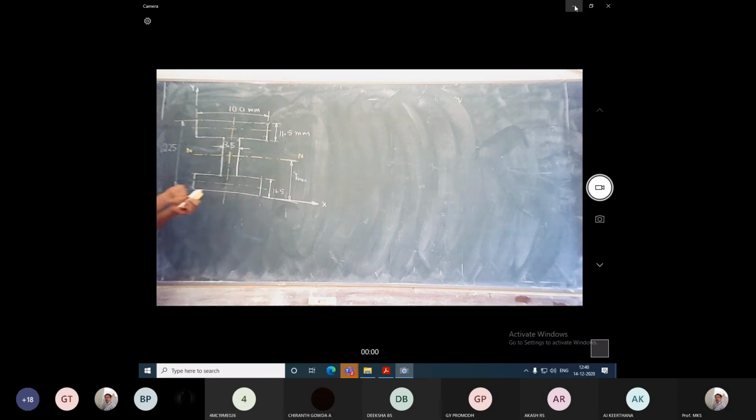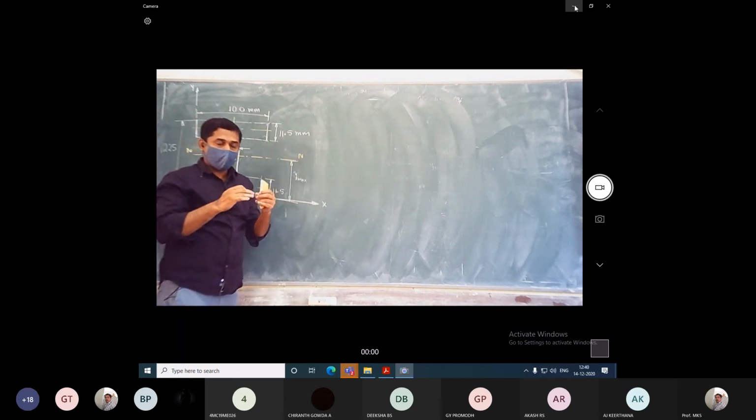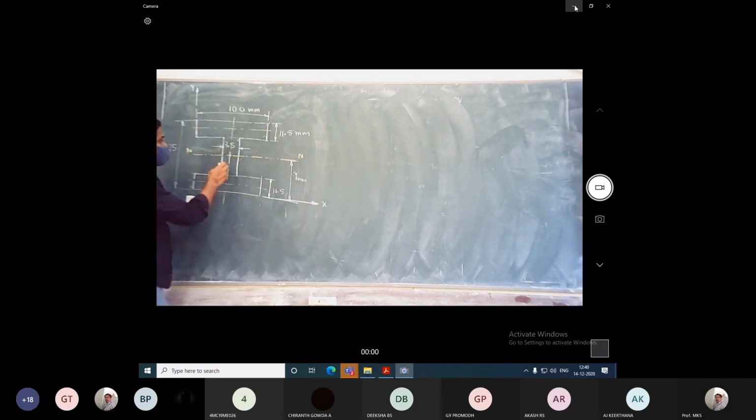Whenever the beam is a straight beam, the neutral and the centroidal axis will be merging, in the same line. So let me mark the centroid point as C. For a straight beam, they are on the same line; for a curved beam, the neutral and centroidal axis will be shifted by a certain eccentricity. So let me mark that centroid as C. Okay.